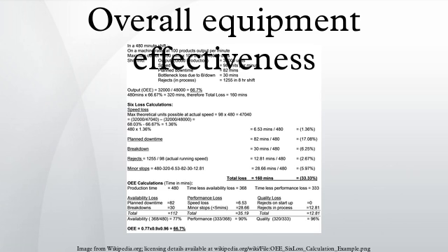Alternatively, and often easier, OEE is calculated by dividing the minimum time needed to produce the parts under optimal conditions by the actual time needed to produce the parts. For example, total time, 8-hour shift or 28,800 seconds, producing 14,400 parts, or 1 part every 2 seconds. Fastest possible cycle time is 1.5 seconds, hence only 21,600 seconds would have been needed to produce the 14,400 parts. The remaining 7,200 seconds or 2 hours were lost. The OEE is now the 21,600 seconds divided by 28,800 seconds, or 75%.